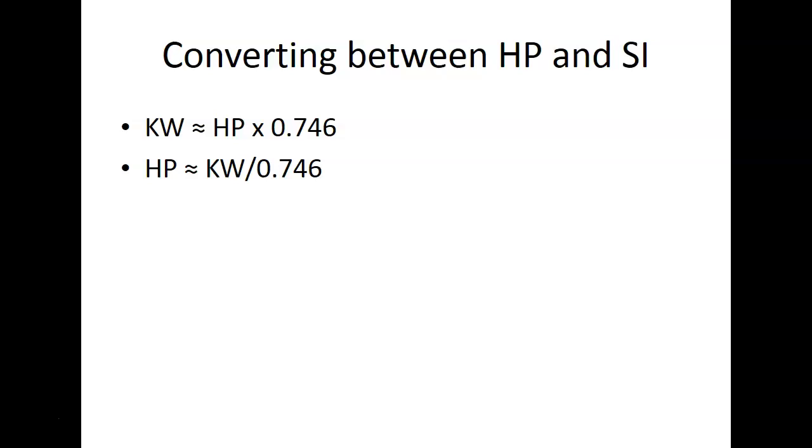And so we can calculate horsepower to kilowatts by learning that one number. Are we okay? Yes or no? So on kilowatts equals horsepower, instead of multiplying by 746 and dividing by 1,000, we always use 0.746, which gives kilowatts. But you can still do it that way.